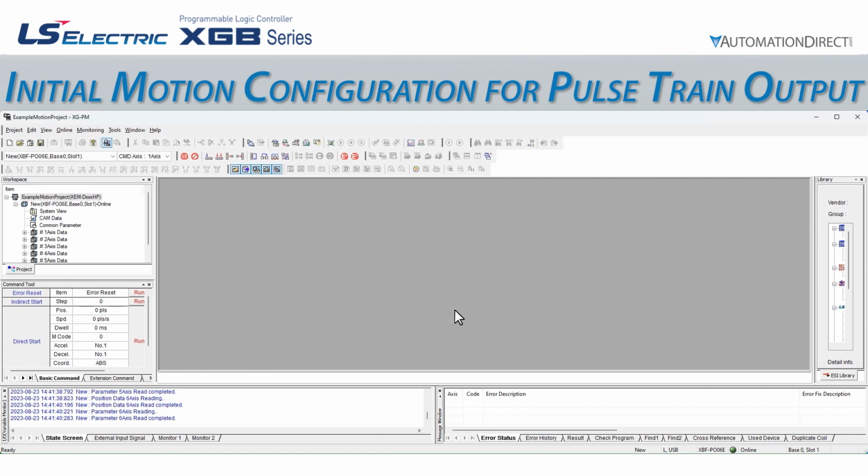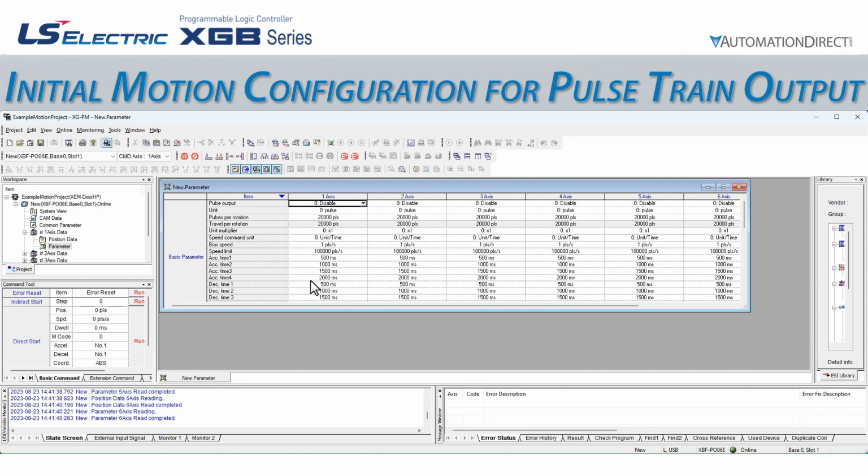We need to set up an axis with initial parameters. To do this, we will go to the project window on the left side of the screen, expand number 1 axis data, and double-click on parameter. The new parameter window opens showing all 6 axes. We will select the drop-down for pulse output under the 1-axis heading. We can then select Enable. This enables this axis for use with the XGPM and XG5000 projects.